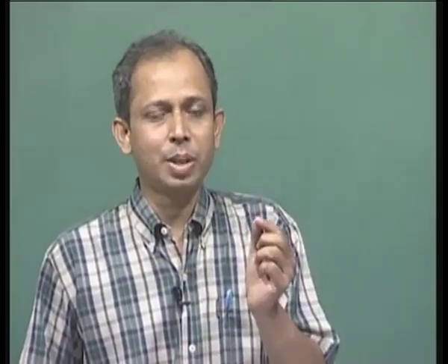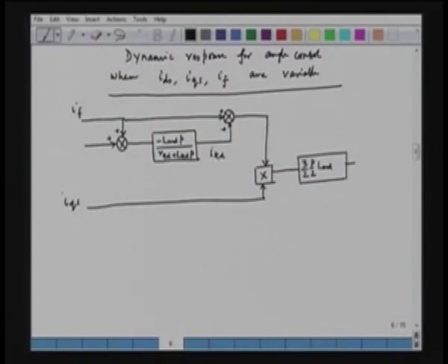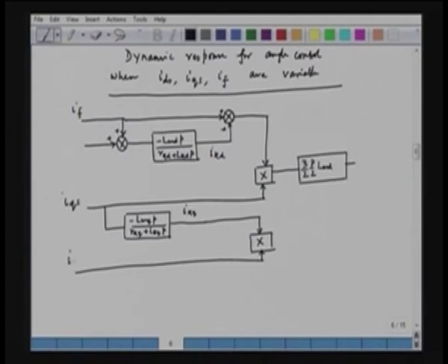Now, how is IKQ coming into the picture? Because IKQ is the Q axis damper current, and that comes into the picture because of the change of IQS, the Q axis stator current. So, because of the change of IQS, we will have IKQ equal to minus L_MQ p over (R_KQ plus L_KQ p) times IQS, and this IKQ is again multiplied with IDS, and this is multiplied with a constant 3/2 P/2 L_MQ. So, this is the second term.